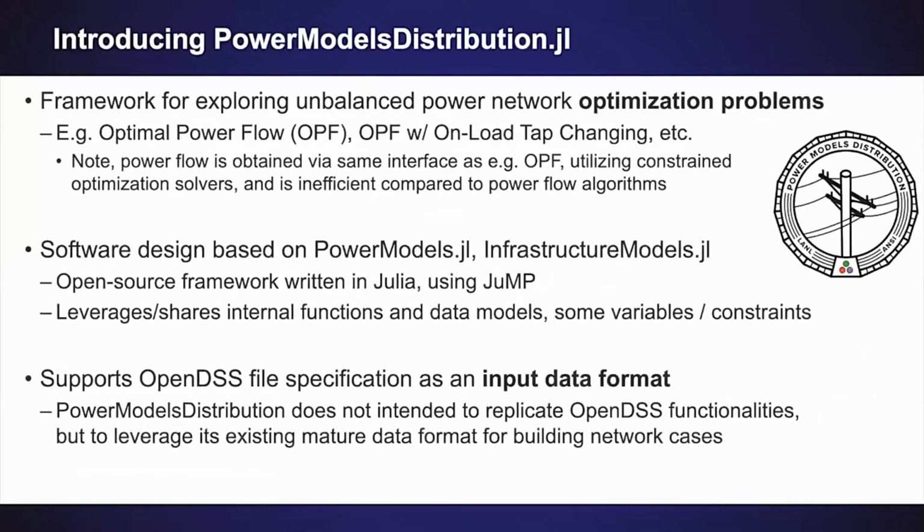So in response to the needs for an optimization-focused tool for distribution, and following the example of PowerModels, we built PowerModels Distribution, focused primarily around exploring unbalanced power network optimization problems, such as optimal power flow, OPF with on-load tap changing, and others. As a small side note, we do include a power flow solver, but because it uses the same interface as the optimization problem, it is much more inefficient compared to dedicated power flow algorithms.